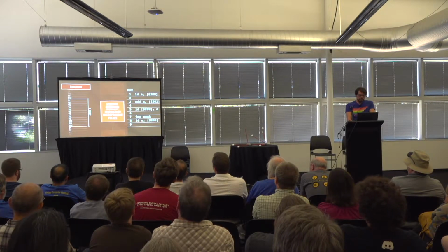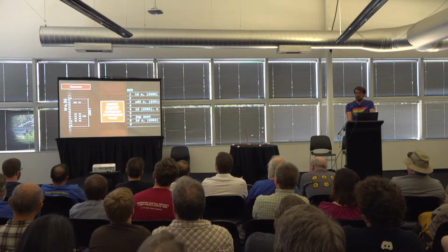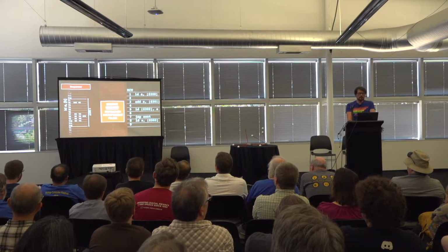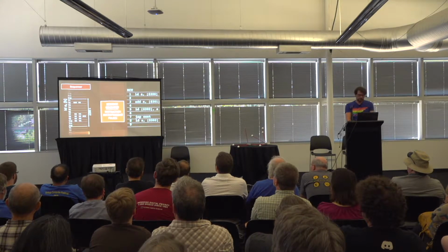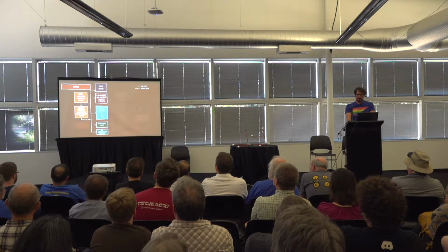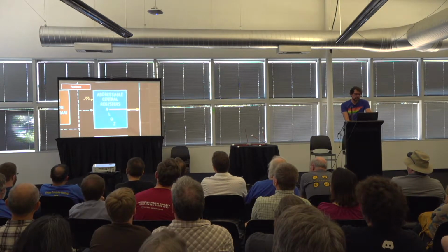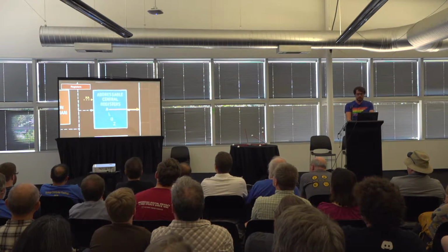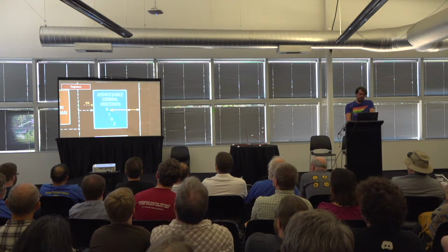The sequence generator contains a collection of 12-step microprograms for each MCT of each instruction, like this one for the load instruction. In each step, the entries send control pulses to the other units, which are connected through the write bus. The control signal RA, for example, instructs the register unit to put the contents of A onto the write bus, and WA makes it write the value on the bus into A.